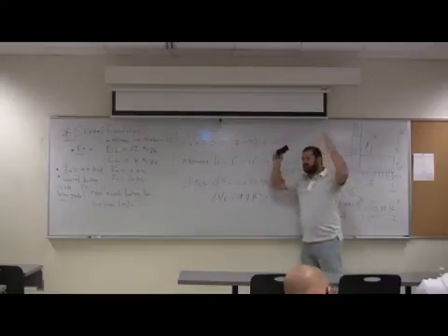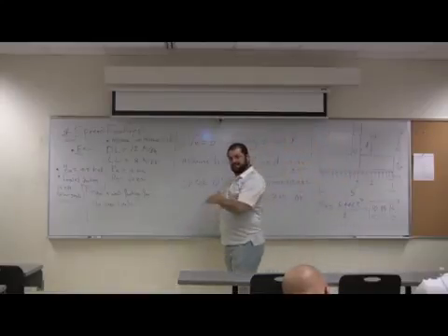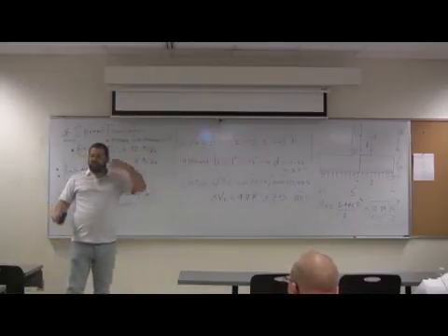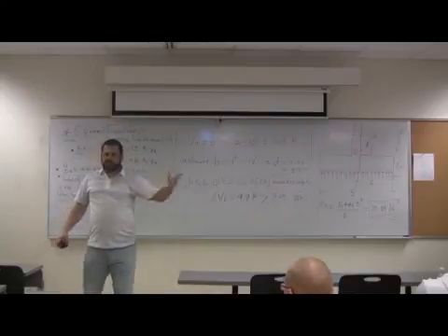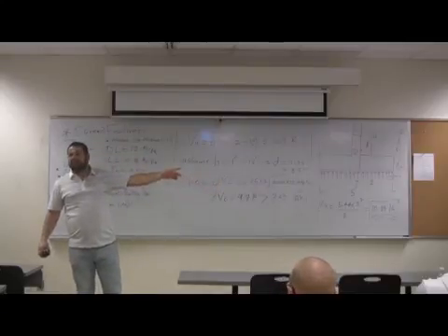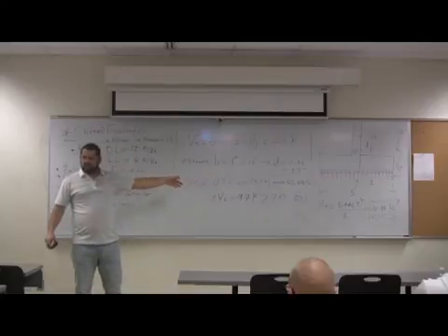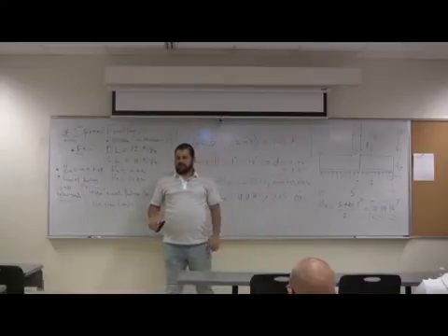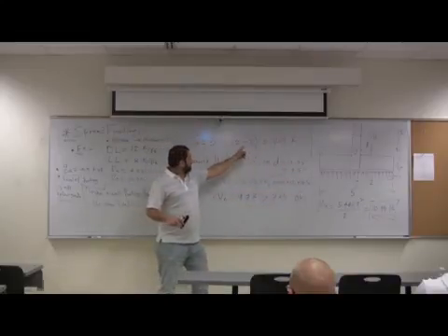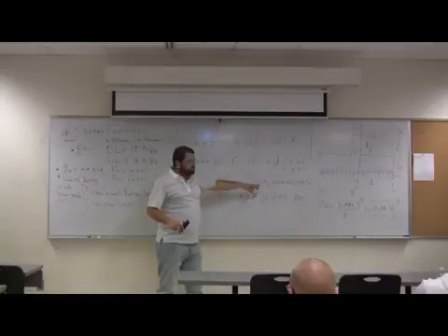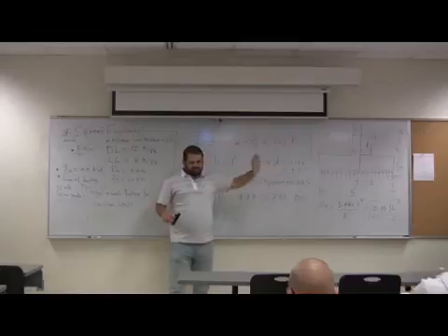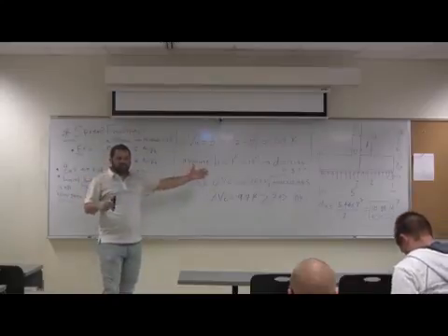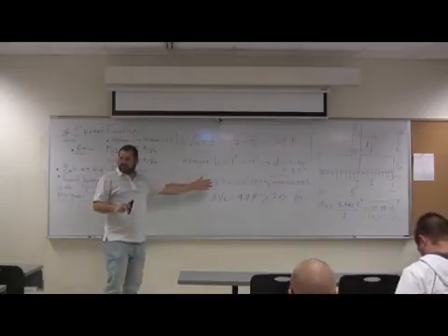Remember, if we are talking about 20 inch thickness, 22 inch thickness, but 1 foot is typical practice in wall footing. If the first assumption for another design was to assume D equal 20 inch, and you get something like that, you may say, I'm going to bring D down to 18 inch, and check it. So the best practice for footing design is assume, check, assume, check. Some may say, keep D as unknown here and unknown in this one, and make them equal to each other and calculate D. Just assume and check. It's just one simple equation. And you have common sense about the assumption. So we are good.